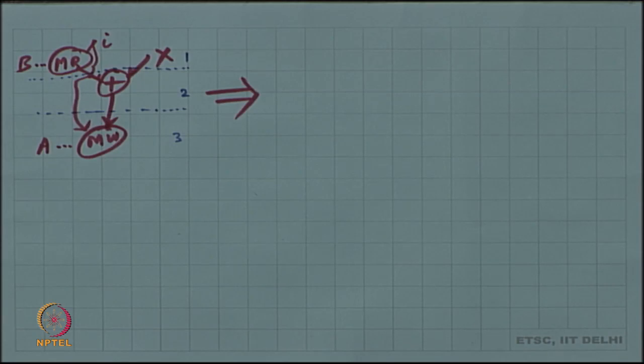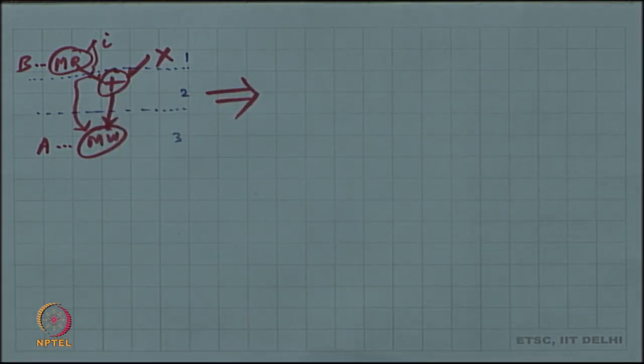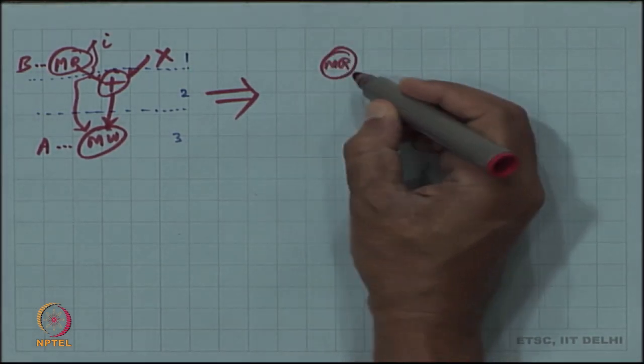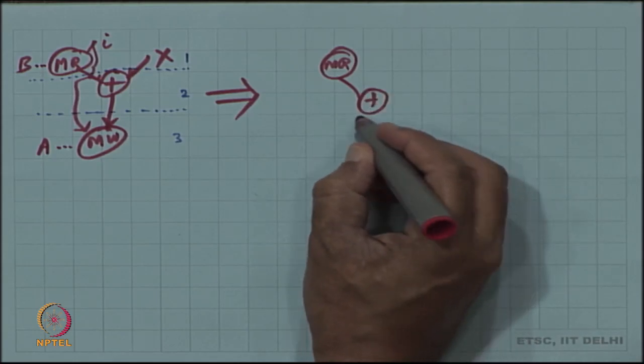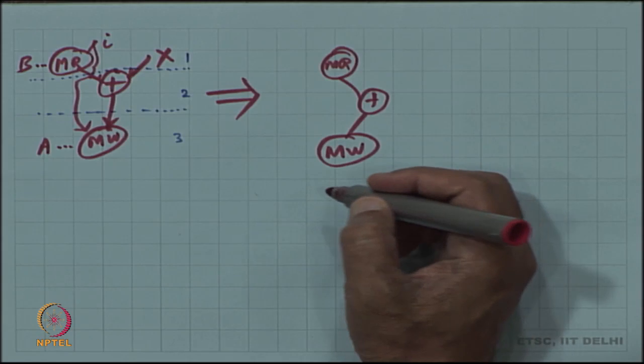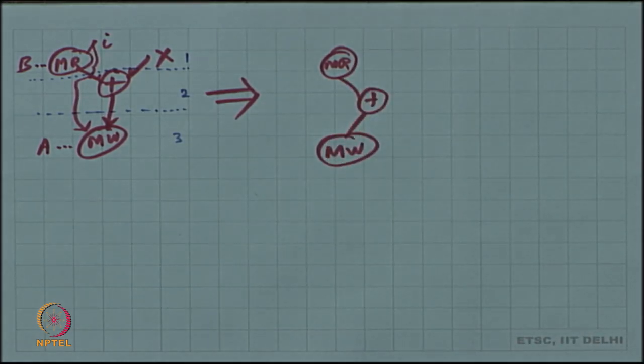What does the DFG of the unrolled loop look like? Yeah, so you actually have the same structure, but it is just duplicated. This is a read, and then this addition is still there. But to the memory read operation you still have to provide an address. It is just that you know the addresses since you have expanded I out.